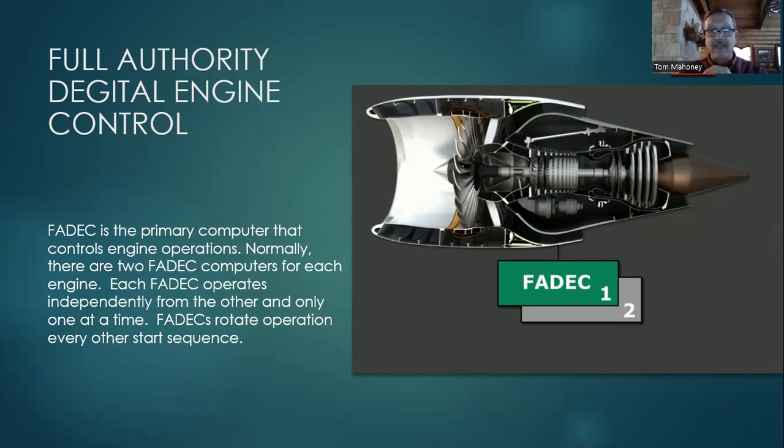So now we have a backup in case we lose one FADEC. The other FADEC continues to step up and then takes over the operations. Now these FADEC computers actually switch positions as to which one's operating every time you shut down an engine and start it back up. If FADEC 1 had been running before, it shuts down, FADEC 2 comes online, and now it's controlling the engines. If, of course, you have an engine failure or a FADEC failure, the non-operating FADEC would jump in and then begin to operate in place of the failed FADEC.